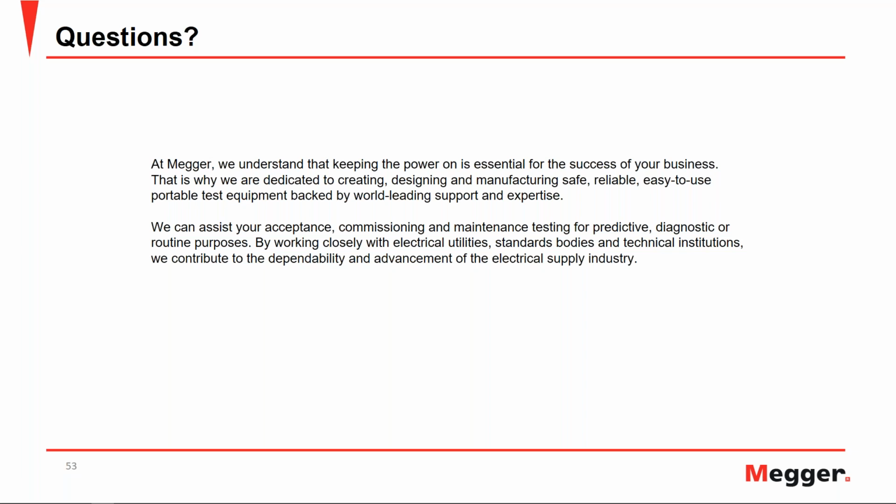And if you remember, the formula for power factor is the cosine of the phase angle between voltage and current. Because of the surface leakage current, the angle between voltage and current exceeds 90 degrees. If you take a calculator and calculate the cosine of 90.1 degrees, you will see a negative value. So those are the reasons why you get negative power factor values.